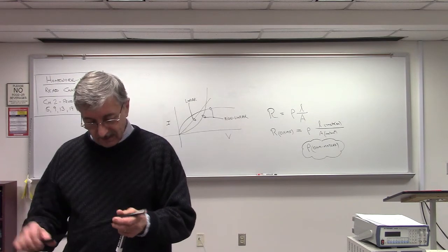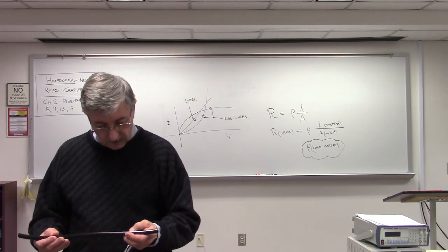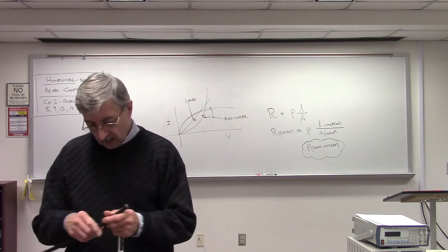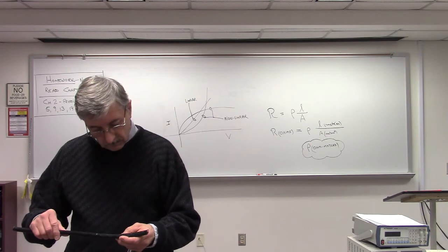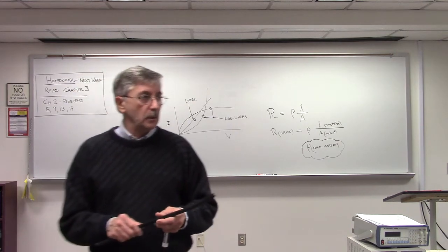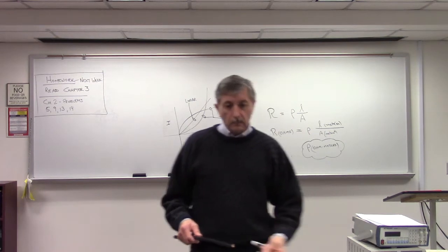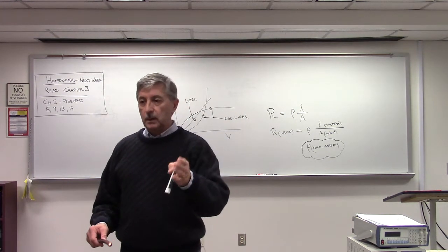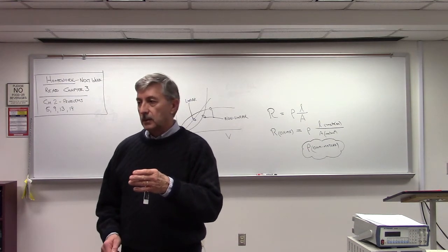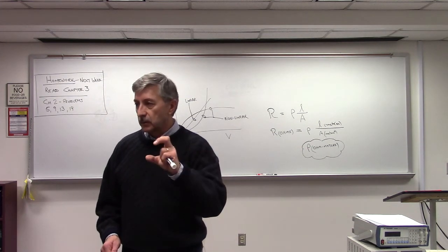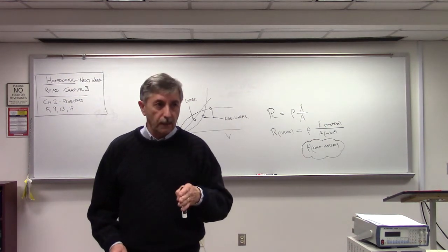This is number 3/0. So when you get, so wire sizes go number 2, number 1, then it actually goes to 1/0, number 0, but nobody ever says that. They say 1/0, all right?